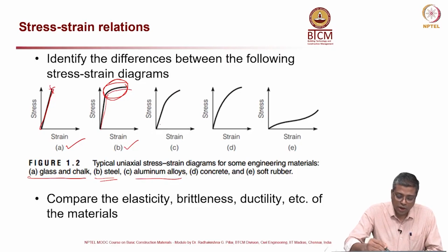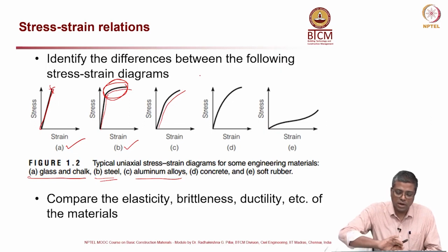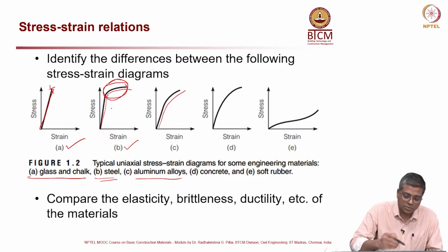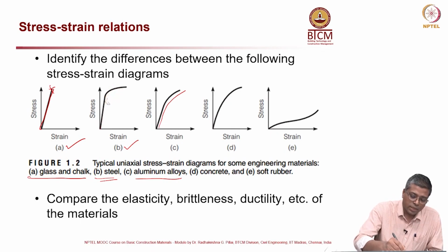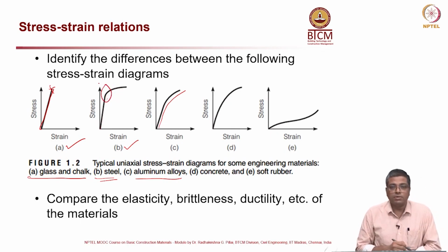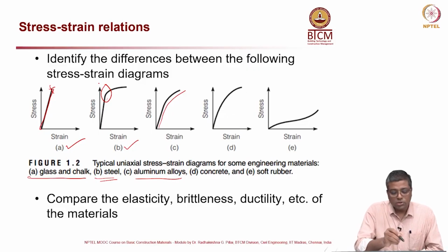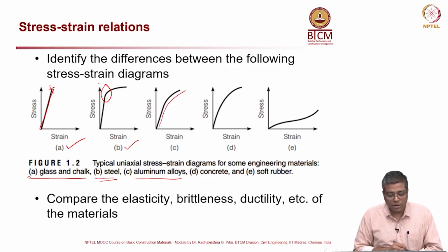Okay. So, in case of aluminum, you can see the curvature in the curve is gradually changing, whereas in case of steel over here there is a relatively sharp change. So, the yield point is better defined in case of steel, and yield point in case of aluminum alloy is not well defined. You have a gradual transition, that is mainly because of the alloys, because alloys means there are different types of bonds in the microstructure.